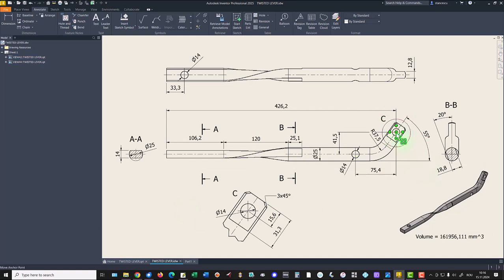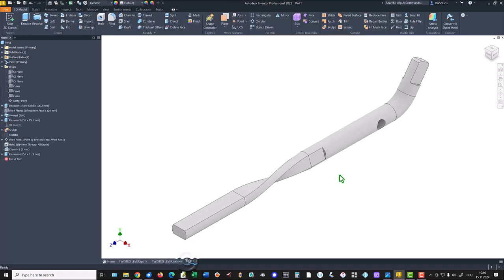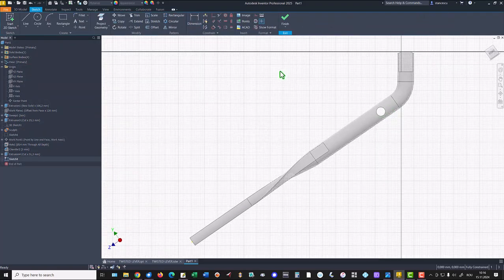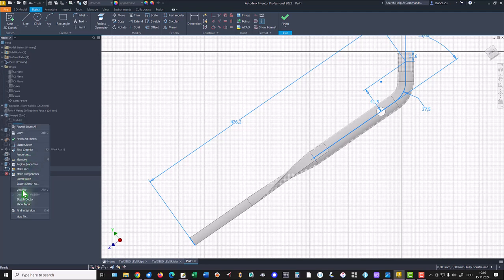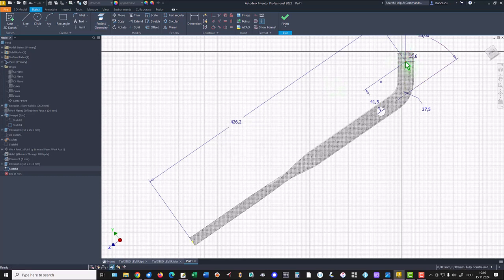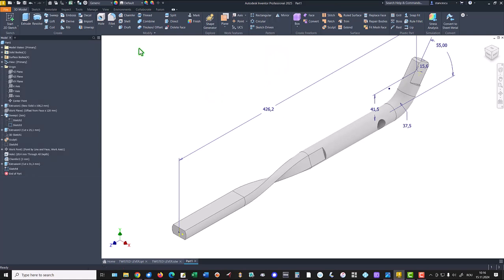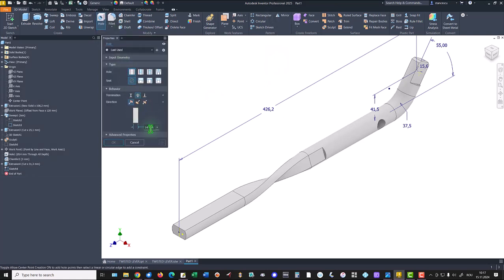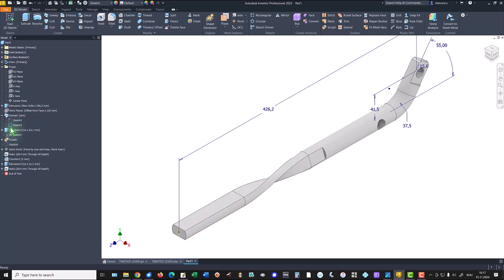Now the hole, this is 1. We select this face, then we open that sketch because we want to project this point. F7 to see inside. We want to project this point. Finish sketch. Hole 14 through the part on this point. Okay, I hide the sketch,